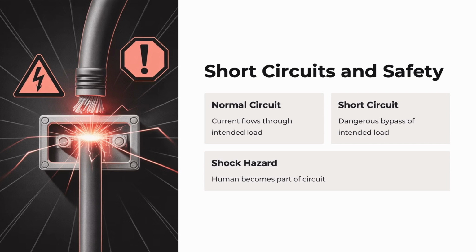It bypasses the intended load entirely and can cause dangerous levels of current flow. And if a person becomes part of that path, you now have an electric shock hazard. How dangerous it is depends on how much voltage is present and the resistance of the person's body, especially if the skin is wet or broken.